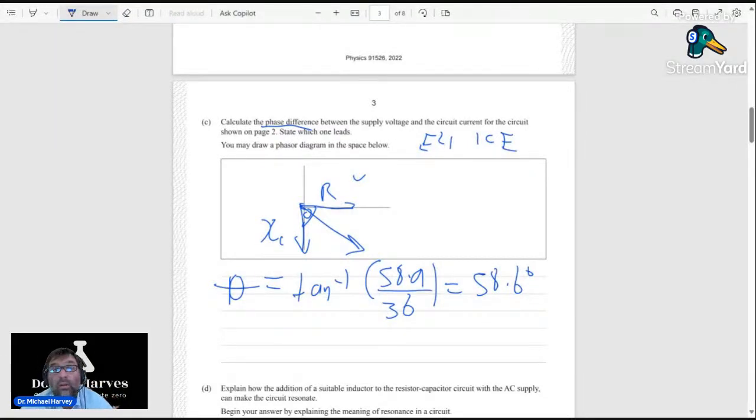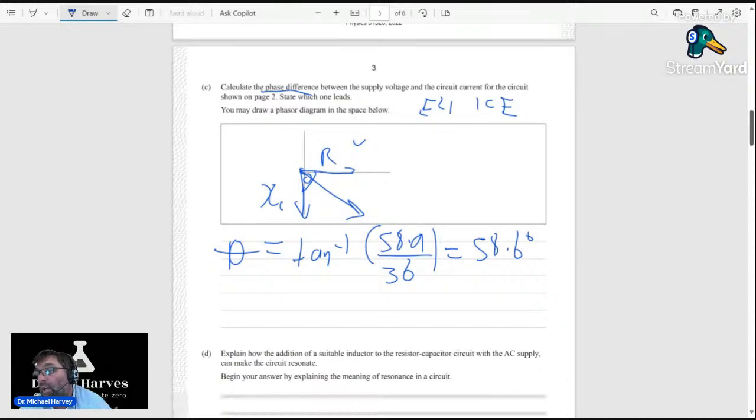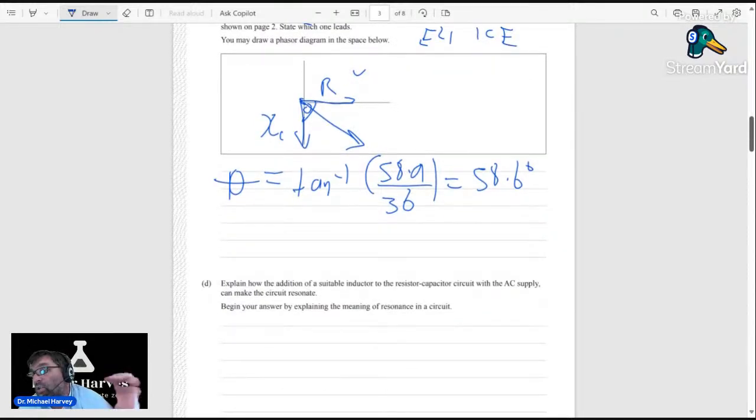It's possible they could have a question on capacitors or inductors completely, or one on an LCR circuit, or they could start off with a capacitor and add an inductor, and you have to calculate the whole LCR circuit in that regard. That's where the phasor diagrams come in.